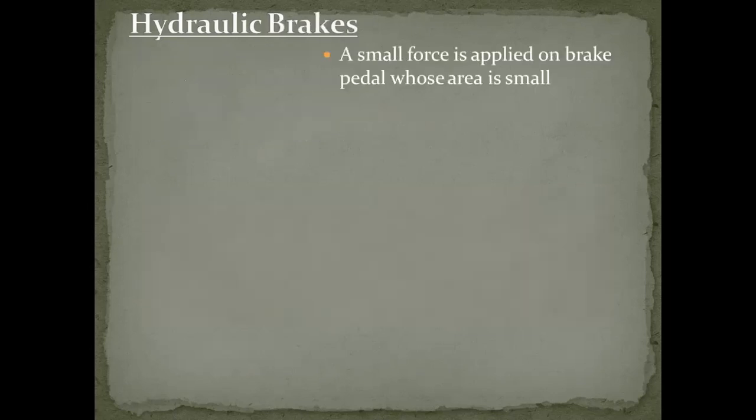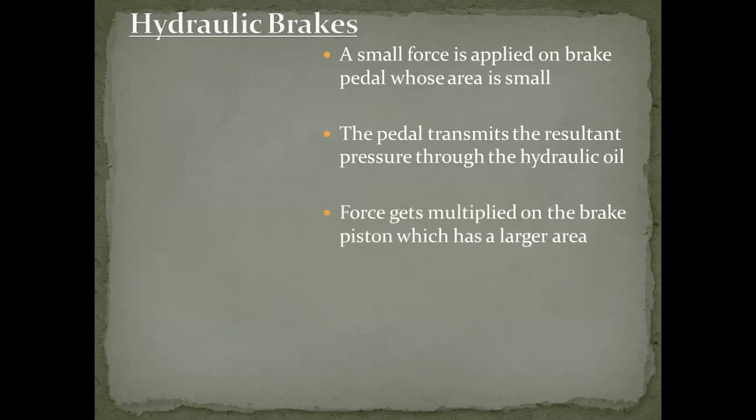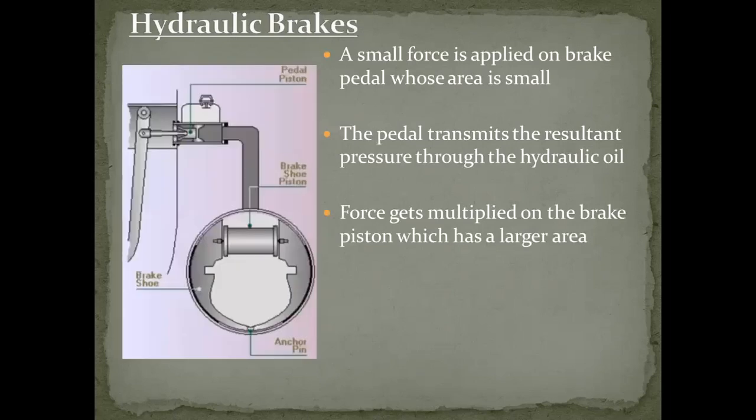Now we will discuss the hydraulic brake. The hydraulic brake works on the same principle. A small force is applied on the brake pedal, whose area is small. The pedal transmits the resultant pressure through the hydraulic oil, and the force gets multiplied on the brake piston, which has a larger area. So here you can see the brake pedal and a small piston, which when we apply pressure, transmits it through the liquid to the brake cylinder, which has a relatively larger area compared to the pedal piston.